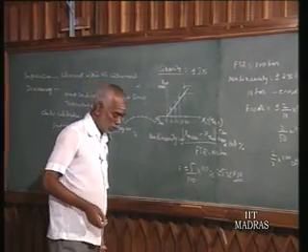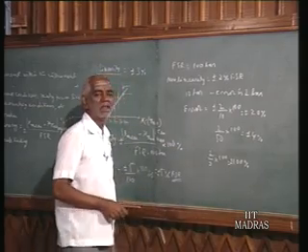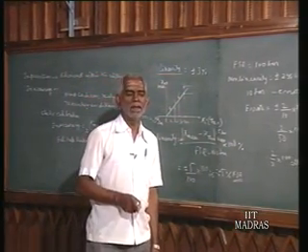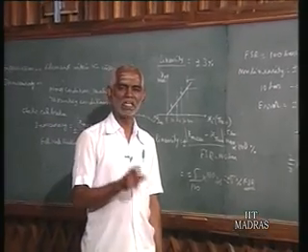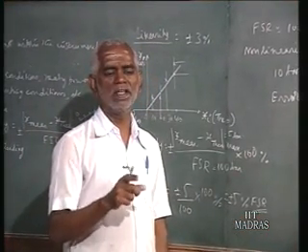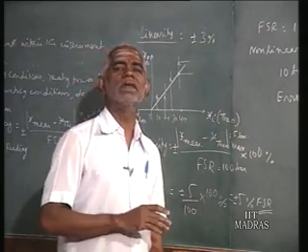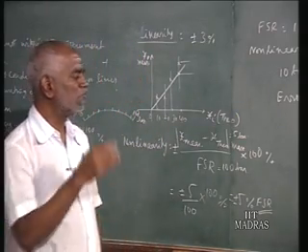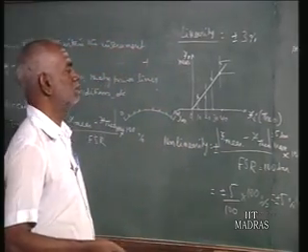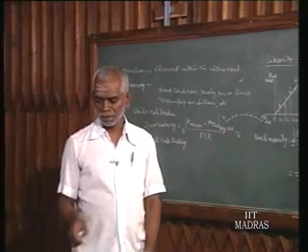Many people do not note this importance. Whenever the inaccuracy or nonlinearity is given in terms of full scale reading, take care that such an instrument is used to read the pressure or input signal above, say, half of the full scale of the instrument. Then only will the reading of that instrument have sufficient accuracy. So this is regarding linearity. Next one.